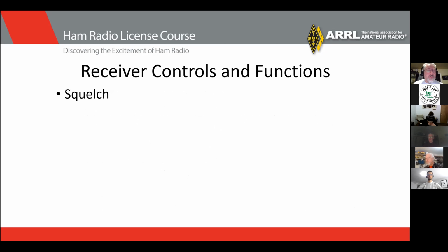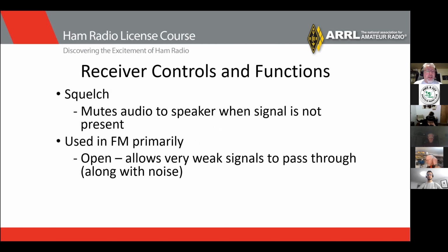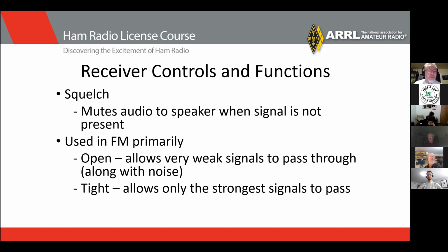There's squelch controls, which mute the audio to the speaker when the signal is not present. Used in FM primarily, and when you open it, it allows very weak signals to pass through along with the noise in the background.